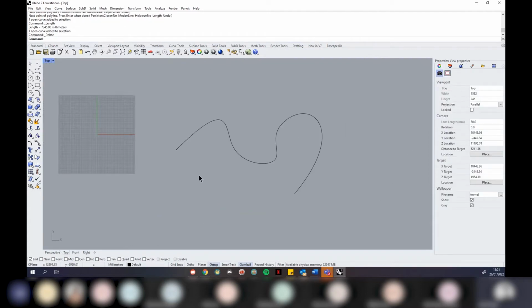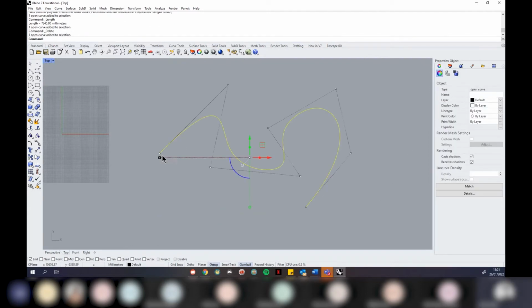It doesn't only work on straight lines. So for instance, I could select this curve here, go to Analyze, go to Length, and it will actually tell me the measurement along the length of this, which is really, really nice because otherwise that would be almost impossible to measure, right? There's no way to kind of stretch this out straight to measure it and to put it back again. But this will tell you the measurement along it. So it's really, really nice.